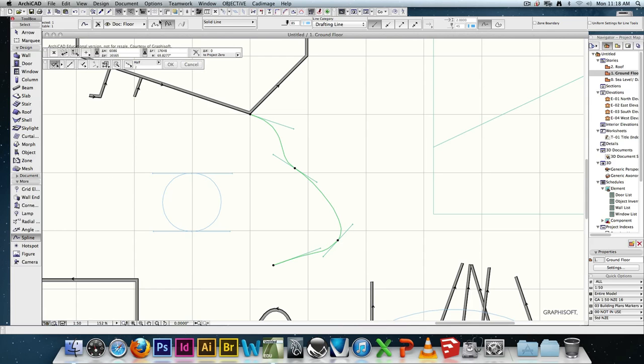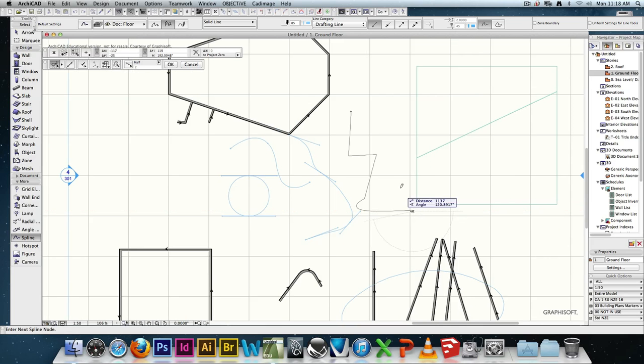But yeah, so that one there's our natural curve. That one there's our Bezier curve. I'm not completely off topic. Note as well, I'm doing a single click and it's doing 90 degree, sharp corners. You click and drag. And at any point, you can actually select one of these and convert it back into a natural curve. It will change its shape though. But yeah, you're going to see these curves all over the place. And we're going to draw contours eventually with these, because as you can see, they're very good for drawing contours.